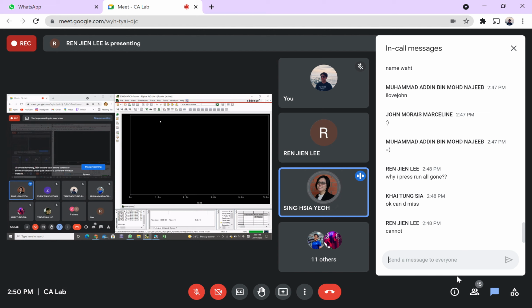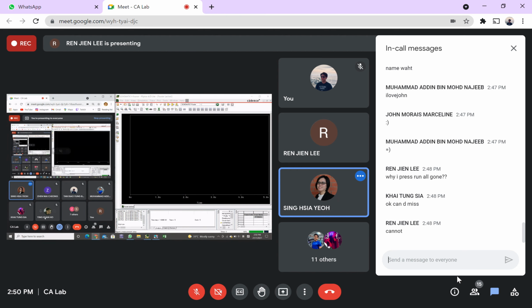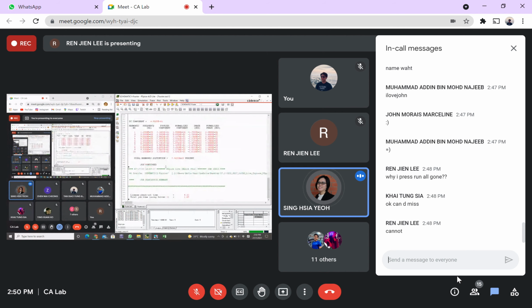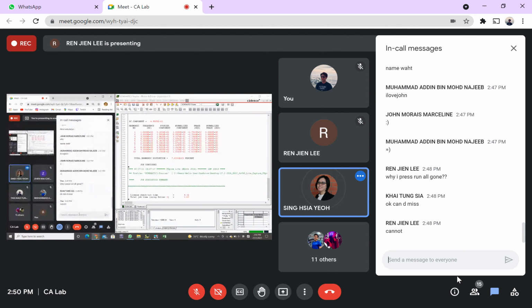You still remember you want to have the plots, then you need to go to trace, add trace. To confirm you are okay or not, go to the view menu on the top, output file. Scroll down. Yes, you are okay. This is the result.